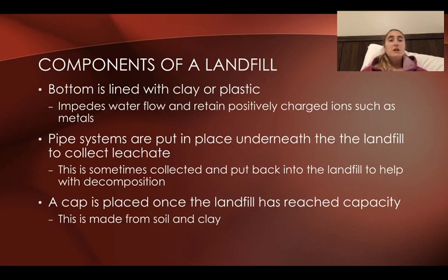But basically they'll dig a hole and they'll determine approximately how much trash is being produced daily per capita, and they'll determine how big the hole needs to be based on how long they want that landfill to be in operation and how much municipal solid waste they think it'll hold. So a landfill may have a 40-year capacity, it may have a 60-year capacity based on what the average municipal solid waste production is per capita for that time frame, and they may include potential population increases and things like that. So they dig this big hole.